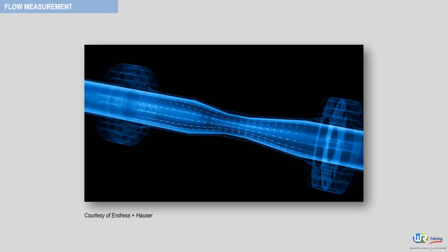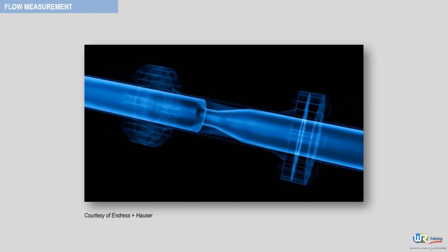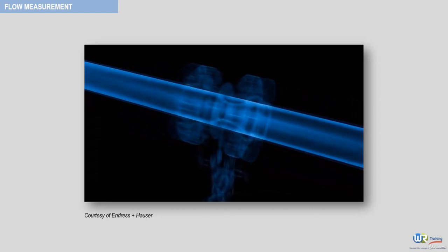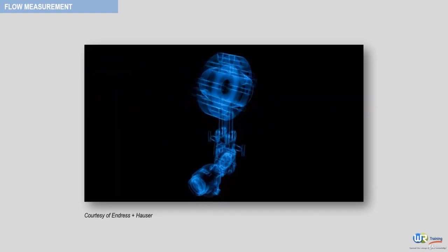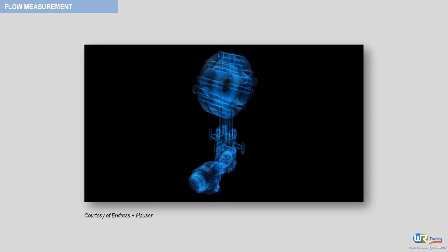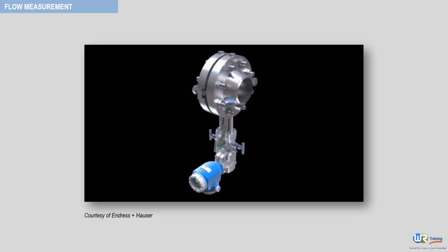All these designs can be supplied with different diameters and sizes so that the pressure loss and the differential pressure generated can be optimized for the process conditions. With this measuring principle, all liquids, gases or steam can be measured even at extremely high process pressures and temperatures.